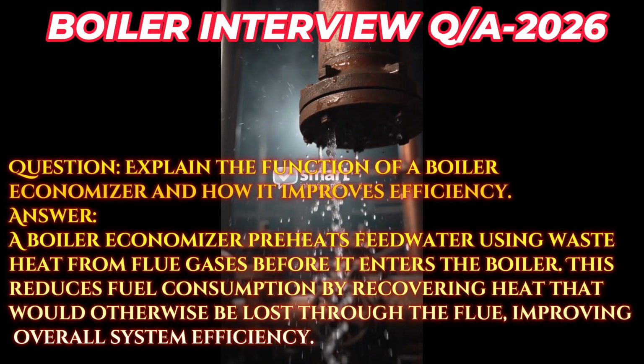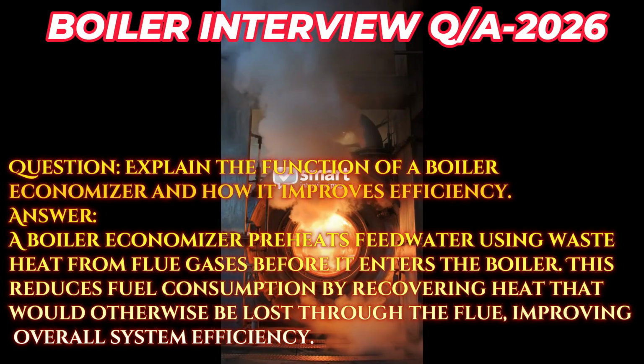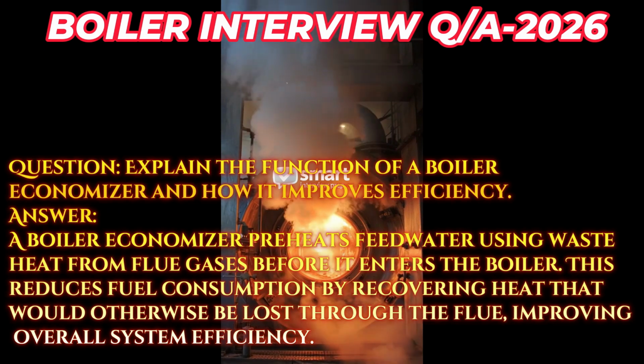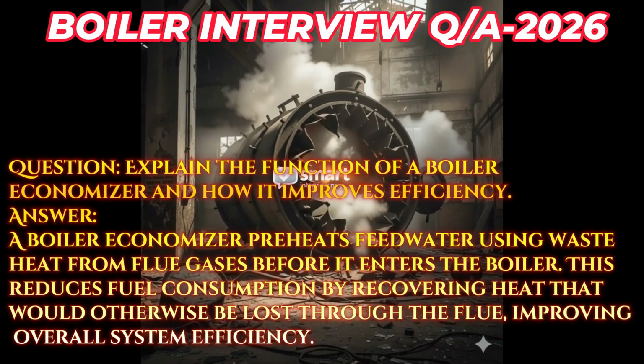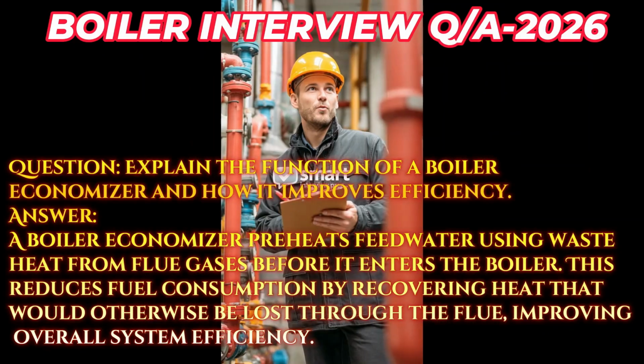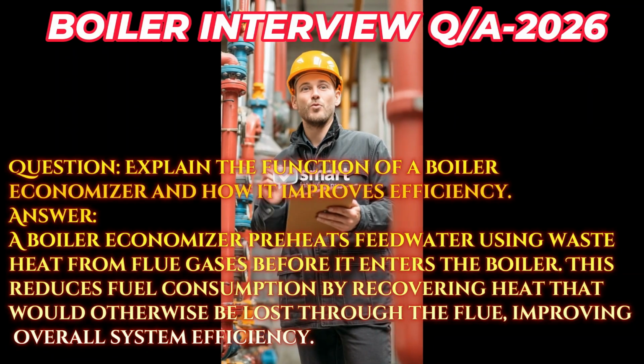Question. Explain the function of a boiler economizer and how it improves efficiency. Answer. A boiler economizer preheats feedwater using waste heat from flue gases before it enters the boiler. This reduces fuel consumption by recovering heat that would otherwise be lost through the flue, improving overall system efficiency.